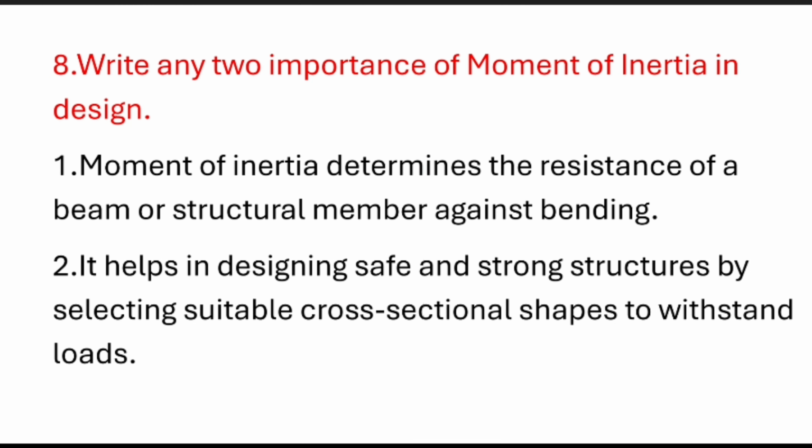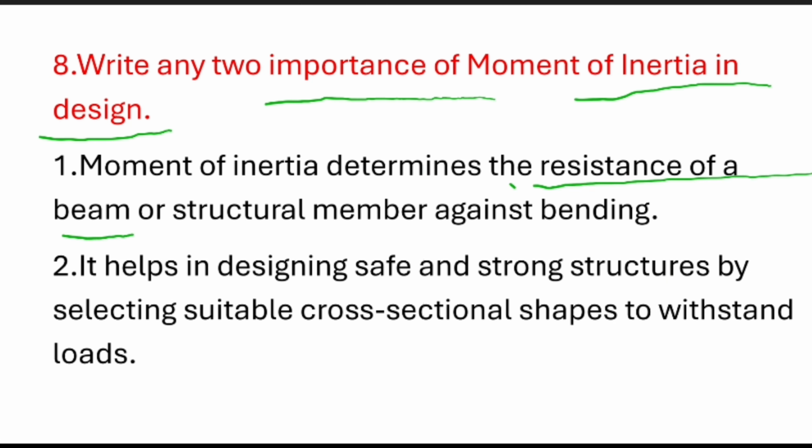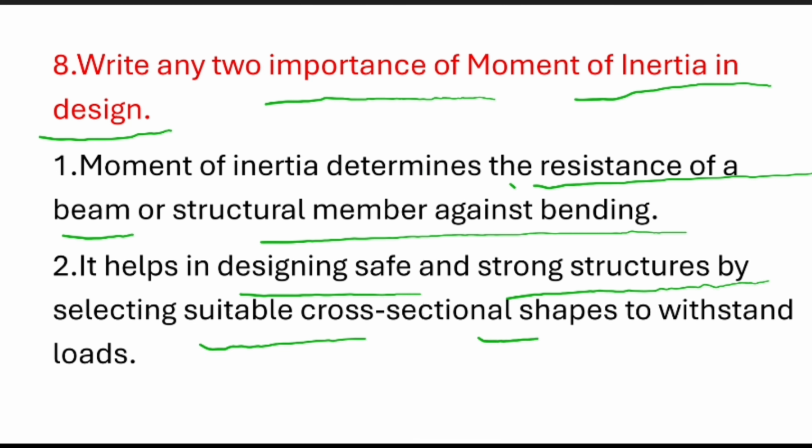Next, coming to write any two importance of moment of inertia in design. What is the importance of moment of inertia in designing? First, it determines the resistance of a beam or structural member against bending, and it helps in designing safe and strong structures by selecting a suitable cross section shape to withstand the load.